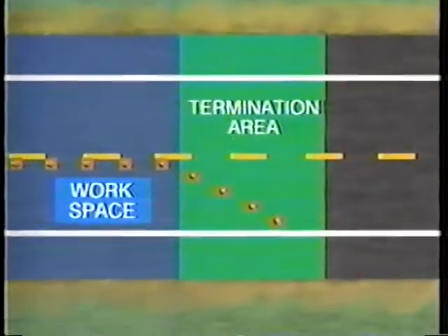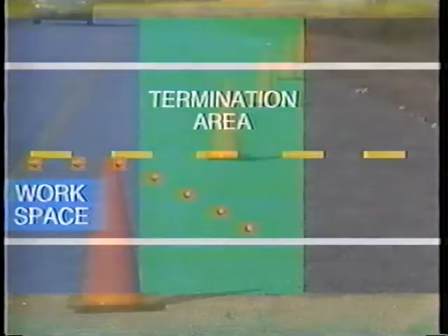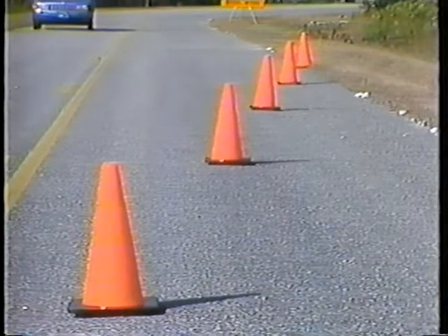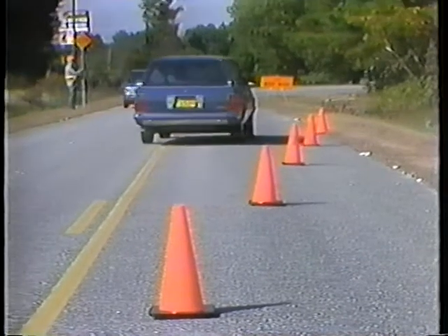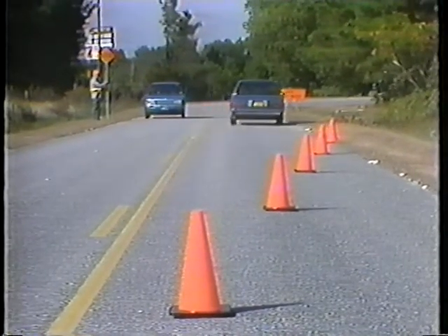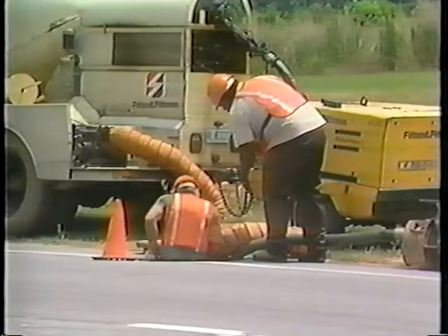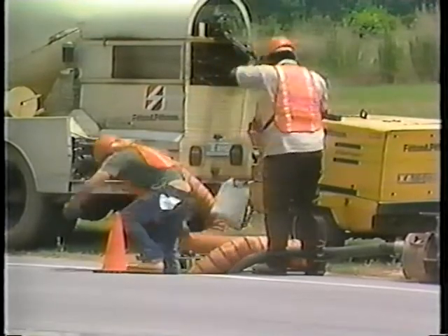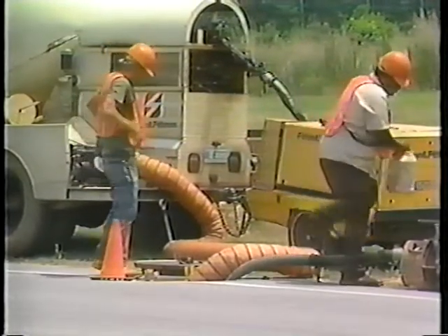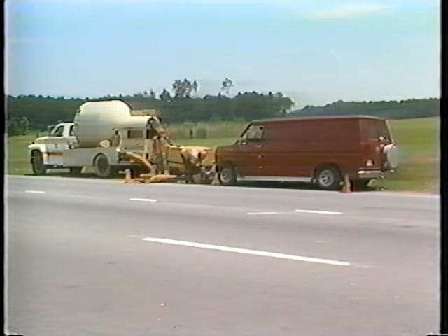The termination area provides a short distance for traffic to clear the activity area and return to the normal traffic lanes. It extends from the downstream end of the activity area to the End Roadwork sign. A downstream taper may be placed in the termination area. For some work operations, such as a single location utility or maintenance repair, it may not be necessary to display an End Roadwork sign because it will be obvious to drivers that they have passed the activity area.